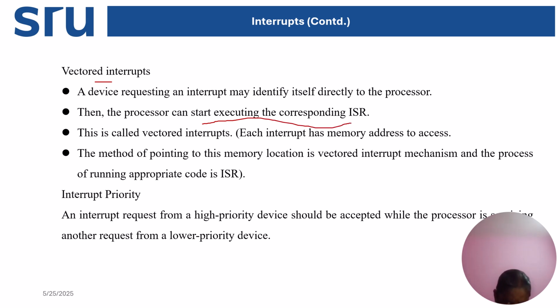Suppose it is a print option, then the printer has an ISR which is stored in a specific memory location. Suppose it is an input operation, for the keyboard a specific ISR is saved in some memory location. Based on the ISR memory address, the processor will vector to the particular ISR. In this way, it identifies which IO device is calling for my service.